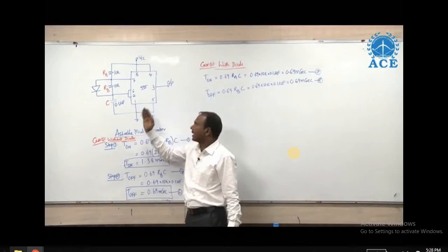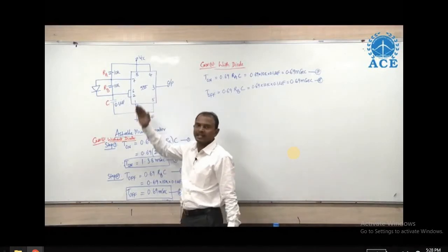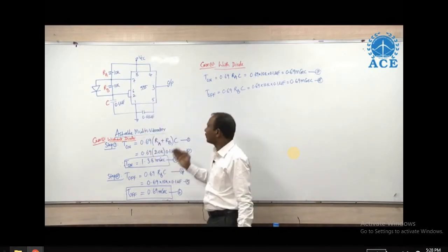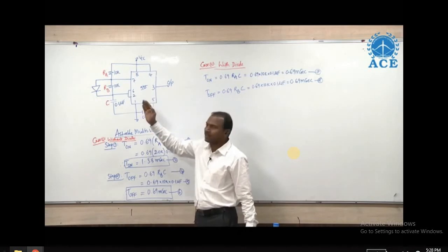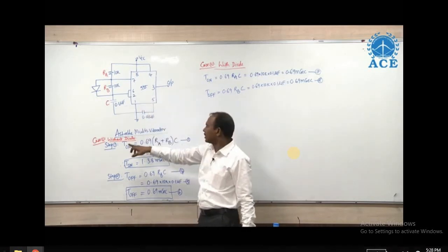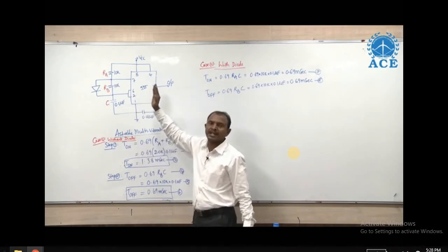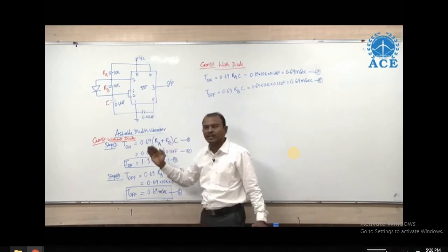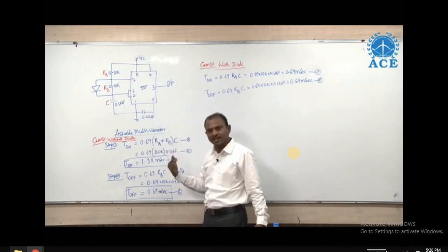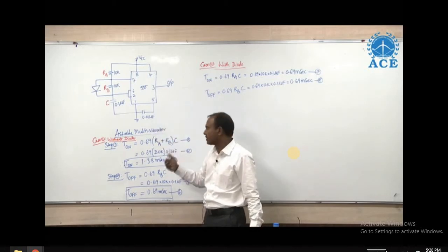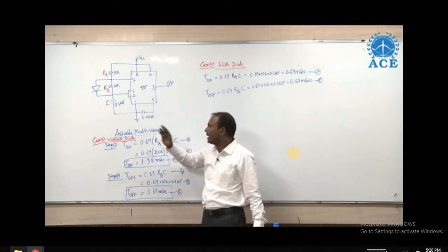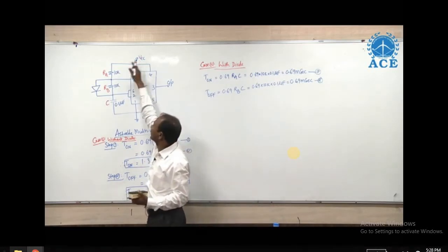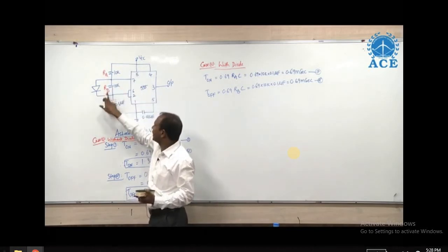In this question, the examiner is asking us to identify the function of the diode in the given circuit. To know that, first let us consider the circuit without the diode. Without the diode, in case 1, it is a basic astable multivibrator. In a basic astable multivibrator, the charging period of the capacitor decides the duration of the positive half cycle, and during charging the capacitor charges from the power supply via RA, RB and C.